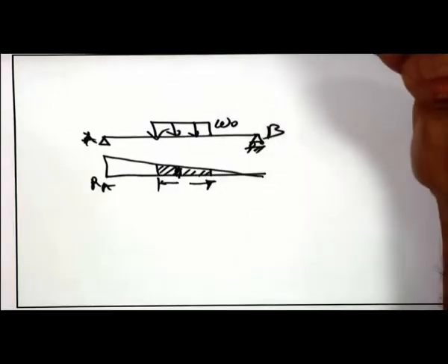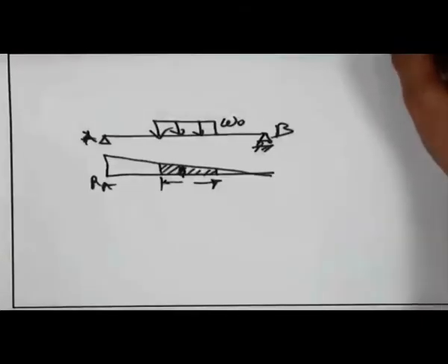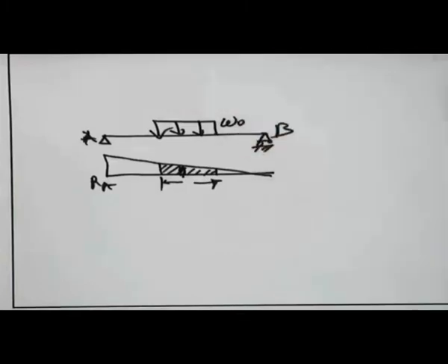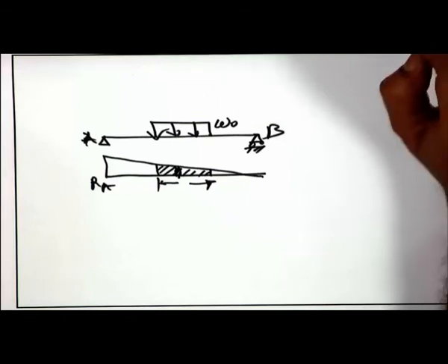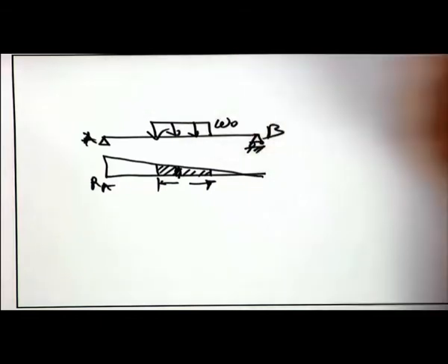So, the area under the curve accounts for the uniformly distributed load. There is no separate diagram for separate loading, probably this was the confusion. You are drawing the influence line diagram for a unit load and finishing it, that is it. You have the influence line diagram ready for concentrated load multiplied by the ordinate. For the uniformly distributed load, find out the area multiplied by the intensity of the load.